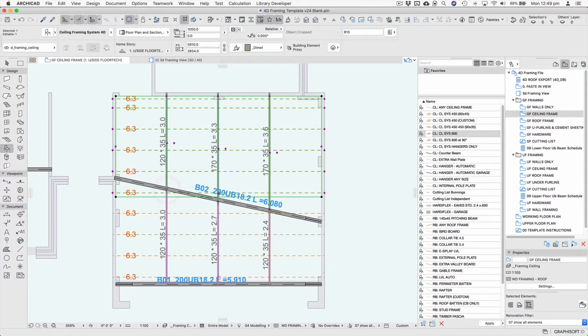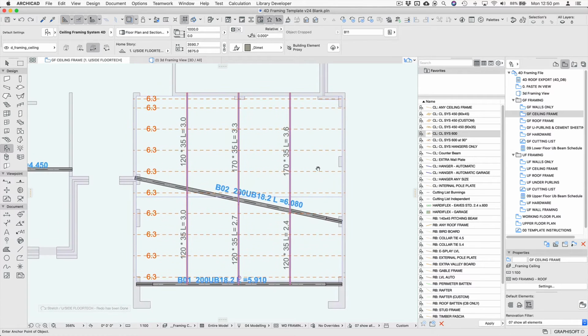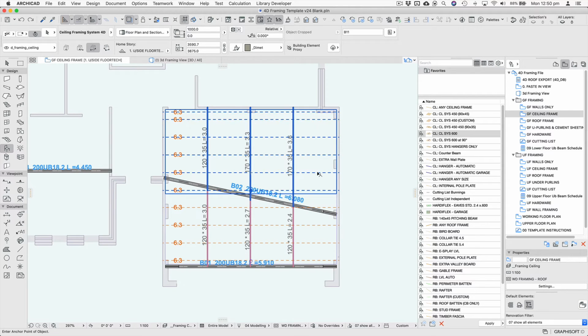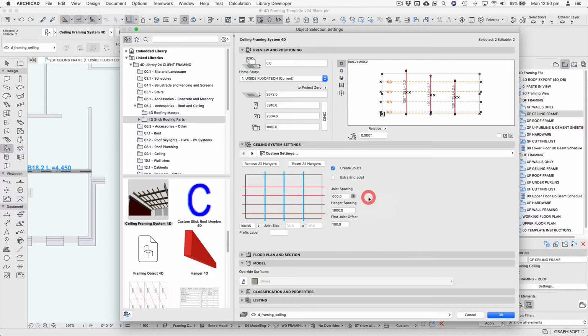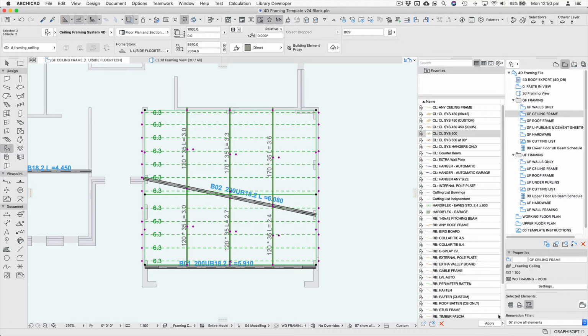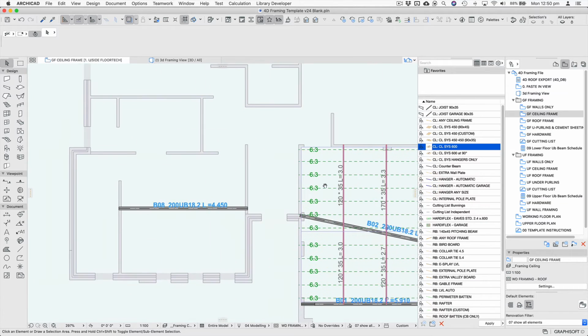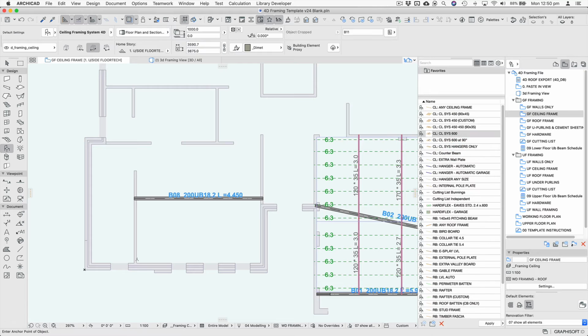Bring this one up. You can see the hangers change size as the length changes. So we've gone from a 190 to a 170, and over there we've got a 120. Actually that is an external area, so we really want to change that to 450 centers. So through here I can just simply change the centers to 450 through there. I've actually got a favorite set up for 450 as well. Okay, so back to 600, up to the beam,